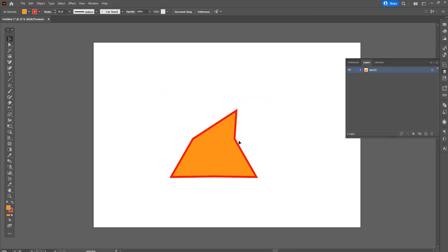Now let's say we want to select multiple corners of this edited triangle. We can do that very easily with the lasso tool. So what we can do is let's move over to the toolbar, left click lasso tool, and move over to our triangle. Now we're going to click and hold to start dragging our lasso. Left click, drag over every point that we want to be able to manipulate here. Then we complete our lasso, release, and as you can see, these 3 vertices here are all now active and ready to be moved with the direct select tool. These 3 hollow ones will not.